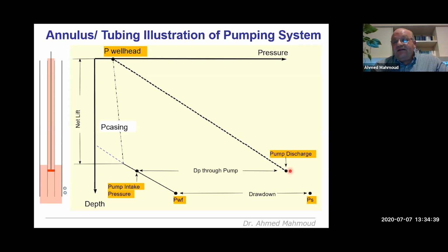It will give you a plus in terms of a boost in delta P, let's say, and then from there on, you will be able to have enough gradient to be able to deliver the fluid to the wellbore with positive pressure as well. And typically this wellhead pressure will be enough to take you throughout the rest of the cycle all the way up through the separator and to the stock tank.